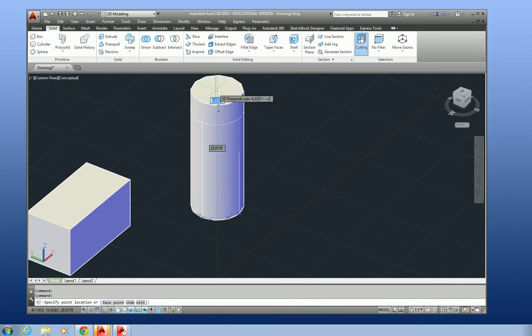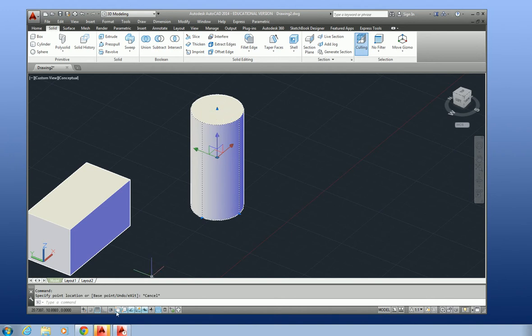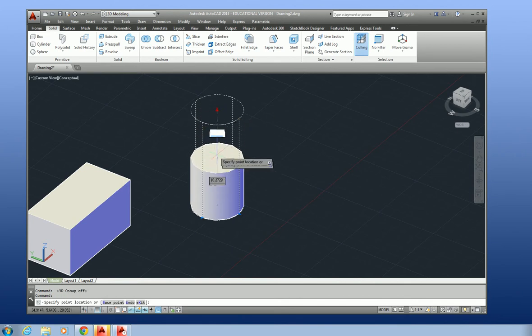And that bottom number, if you'll notice, see how that's snapping back and forth, that craziness? What we need to do here, hit escape, is let's turn off our snaps, because what that's saying is it wants to snap to something. There we go, a lot smoother. So let's hit the tab. That number is the height of this object. So I'm going to key in, let's make this 10 tall and hit enter. So that's how we manipulate our solids that we couldn't do in the past.